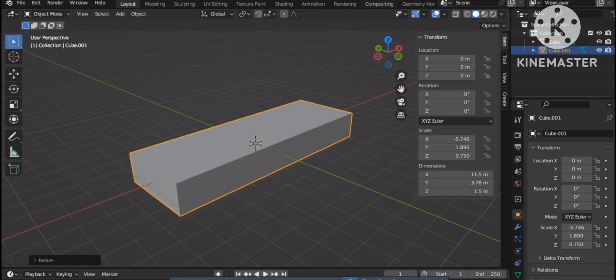Now let's quickly talk about why it is important to have a scale of 1, 1, 1. The problem comes in every time you do some 3D modeling on this object. With the scale not set to 1, 1, 1, that can cause issues when doing things like an inset or a bevel or different edit parameters. I know that sounds a little bit complicated or confusing, but it is always just a good practice to set to 1, 1, 1 scale. Let me show you quickly how easy it is to reset this object scale to 1, 1, 1.